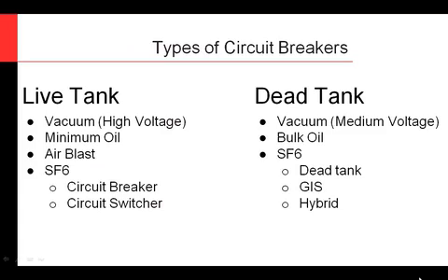And you'll notice that both have very similar insulated mediums. You can have vacuum in live tank, you have vacuum in dead tank. In live tank, you'll have something called a minimum oil circuit breaker, whereas dead tank, you'll have something called a bulk oil circuit breaker. There's something over in the live tank called air blast that there's nothing analogous over in the dead tank circuit breakers. But you'll both have SF6 circuit breakers, and circuit switchers in live tank. Then you'll have dead tank, GIS, or hybrid type circuit breakers over in the dead tank realm.